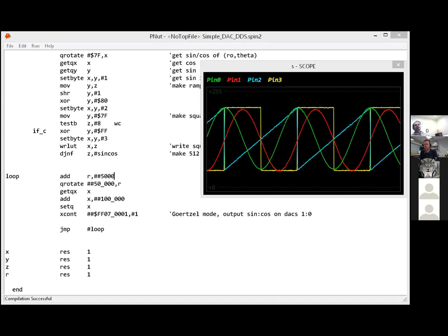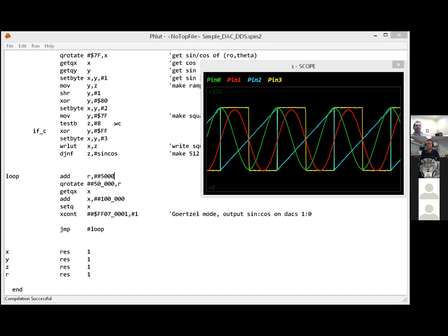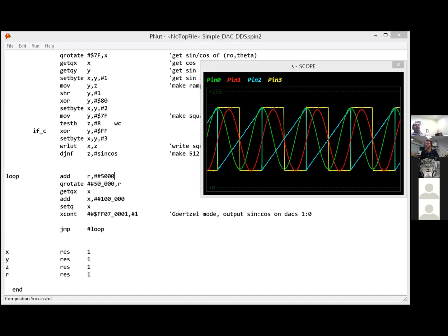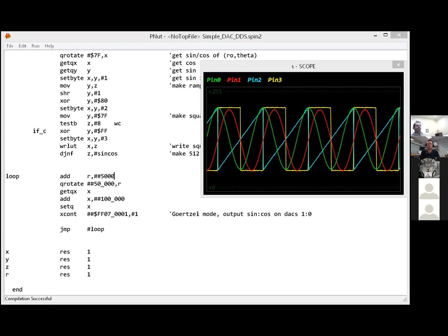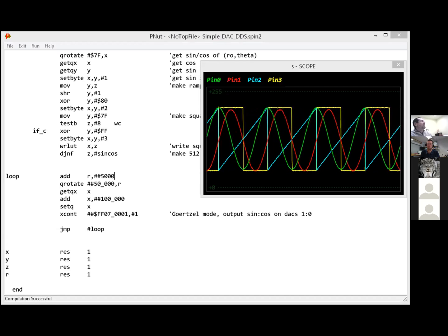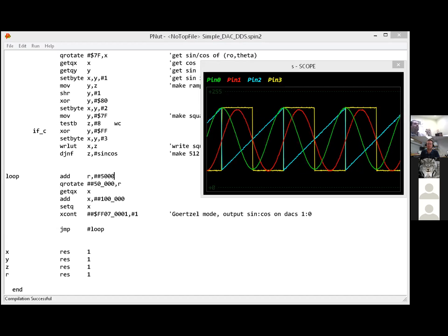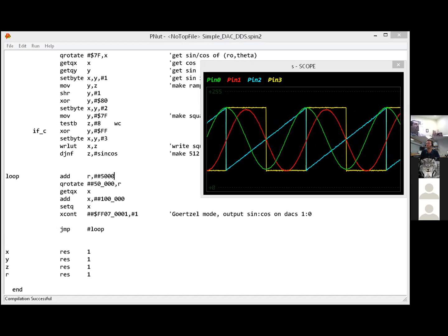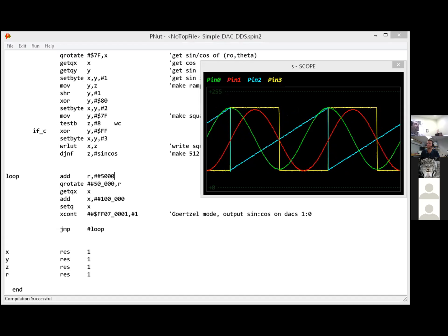Yeah. But you could get a lot lower if you want to get way below 75 ohms impedance. You could do that, right? Because you could tie those DAC outputs together. Yeah, and get lower impedance. Yeah, you could get super low impedance. I mean, you could drive 8 ohm speakers. There are DAC output modes with the streamer where you can say, output just byte 0 from the LUT to all 4 channels. There's lots of combinations like this so that you can gang these things together and make really low impedance analog outputs.